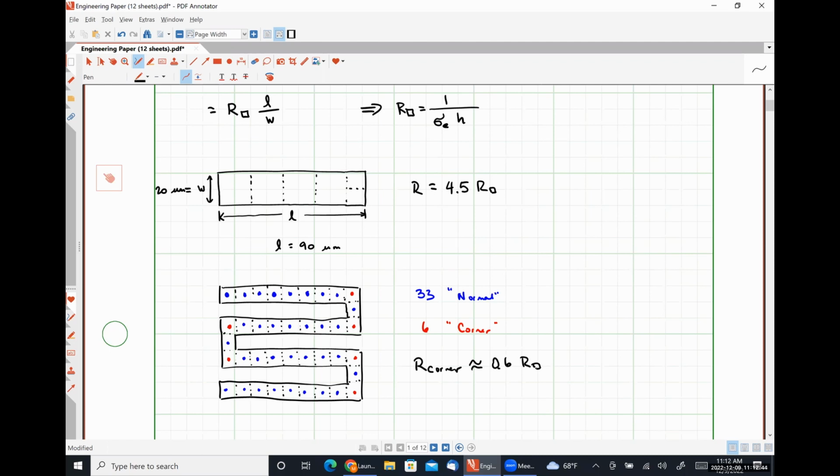Now, you might be asking yourself, well, why would we ever use a serpentine pattern like this, okay? So for my integrated circuits students that had me last quarter, we talked about using serpentine resistances in order to reduce the lateral length of a resistor, right? We're taking up more area, but we're not having to do extremely long runs of a particular material in order to achieve a resistance. In a MEMS device, there's an even better reason, okay?